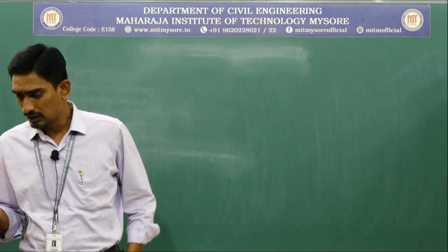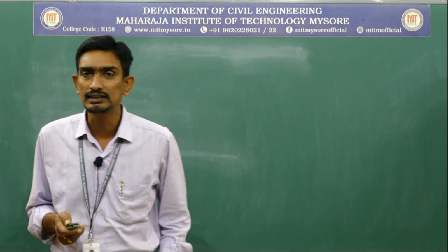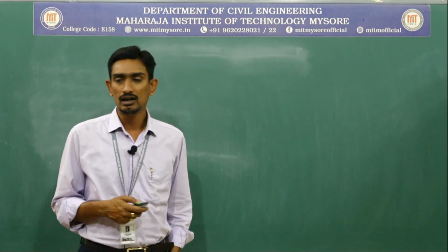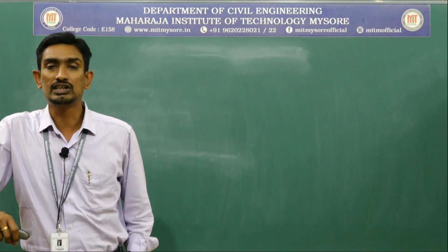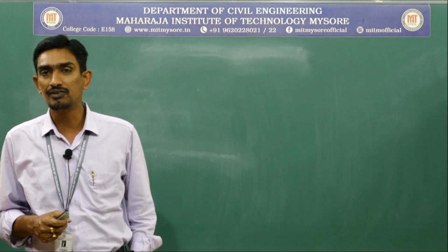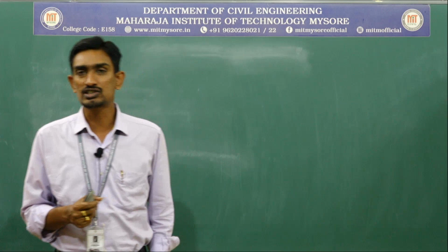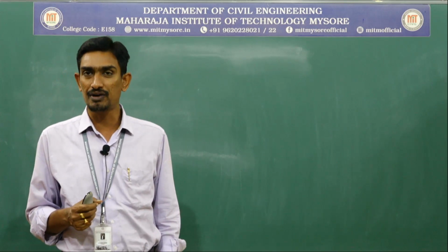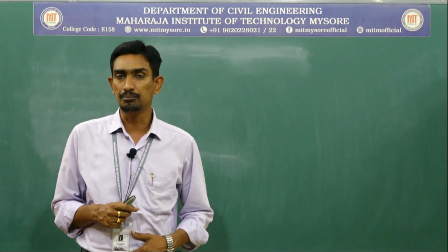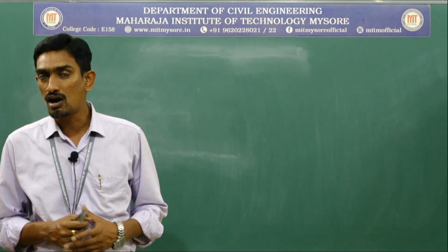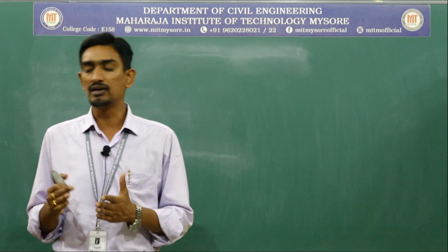So, preferably that is grade A. That grade A has a minimum block density, as you can see from the slide. These are used as load bearing units and shall have a minimum density of 1500 kg per meter cube. And this grade A will have a strength that I think I specified in yesterday's class: the minimum compressive strength a concrete block should possess is 3.5 MPa. Hence the grade A concrete block should possess a minimum strength of 3.5 MPa, likewise 4.5, 5.5 and so on.